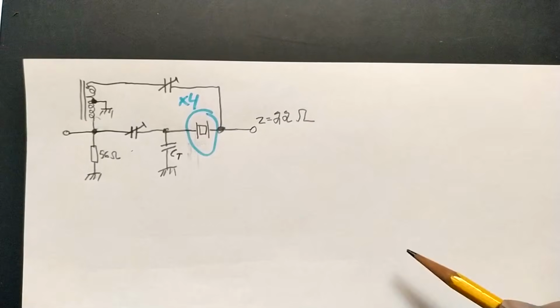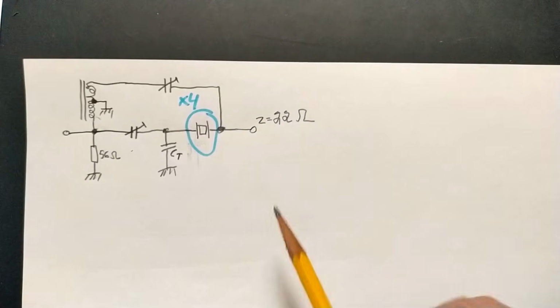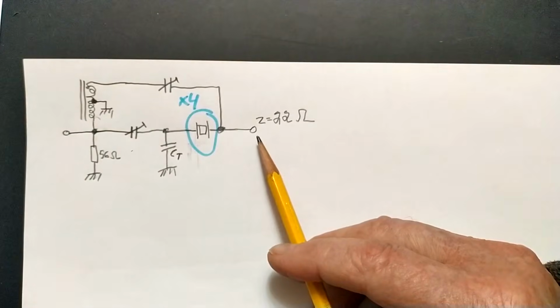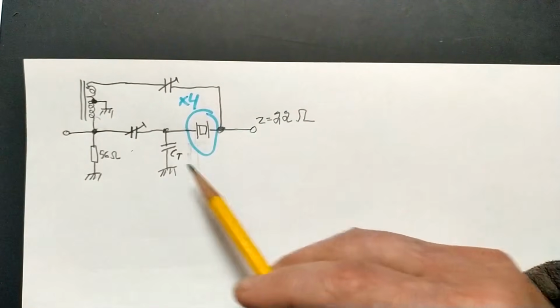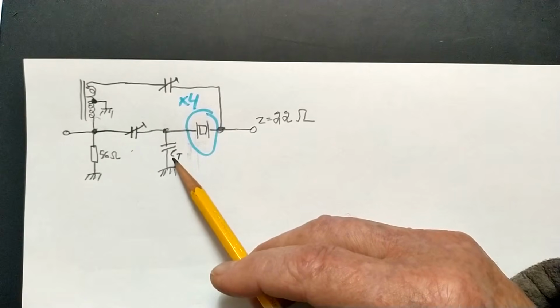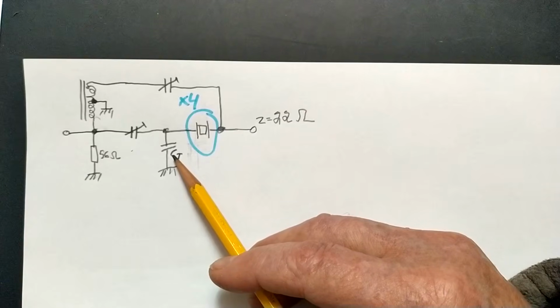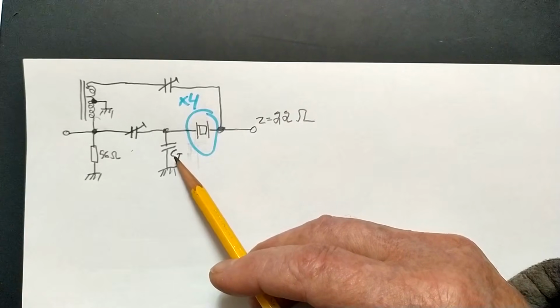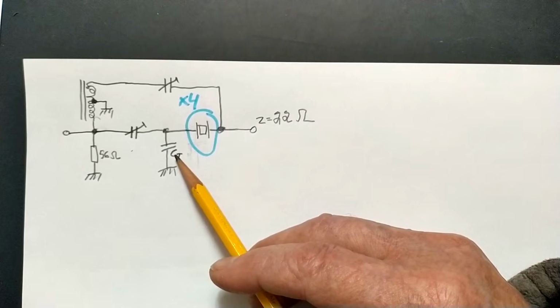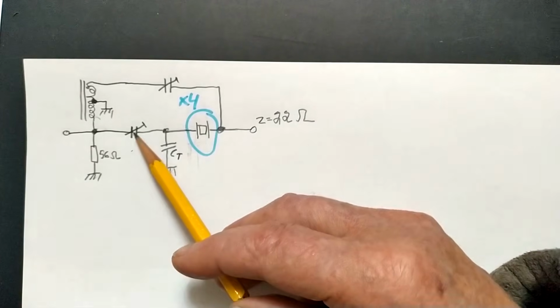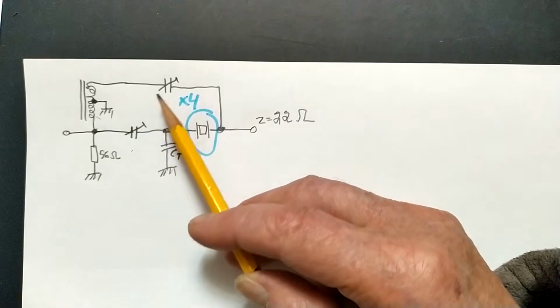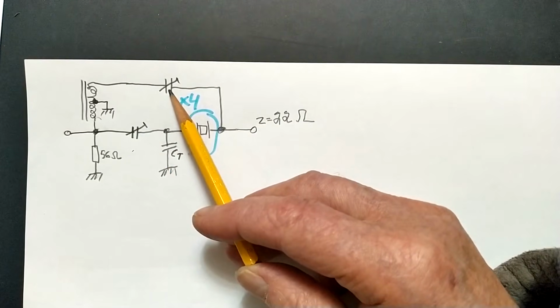This is the crystal filter. The output impedance is resistive 22 ohms, and the tuning capacitor is in the order of 27 pF, I don't remember. It's a fixed capacitor because large tunable capacitors are easily creating noise. And this is the coupling, and this is to get a good suppression in the stop band.